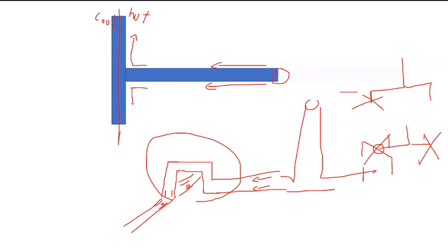Okay, next one, for the stress mark, you see the warpage result or packing result or injection result. I would recommend to check both, because the residual stress can be caused by the thermal and caused by the flow. We need to check both and make sure both of them are fine.